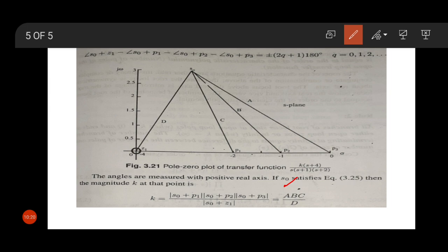However, finding root locus points in the S-plane that satisfy the angle criteria is a very tedious procedure. By using a special tool called a spirule, we can find the set of all points on the root locus. But this trial and error method of drawing the root locus is obsolete. An approximate root locus plot can be drawn using hand calculations with construction rules. In the next lecture, I will discuss the construction rules of root locus.